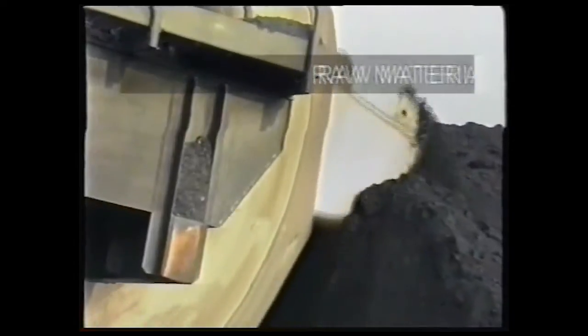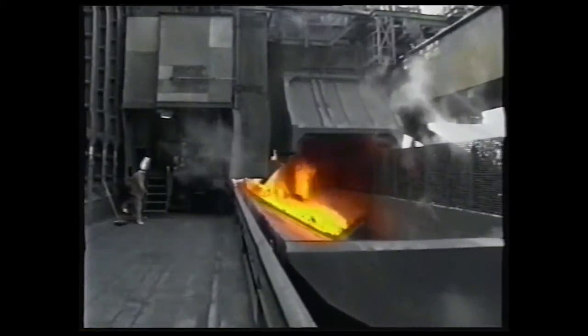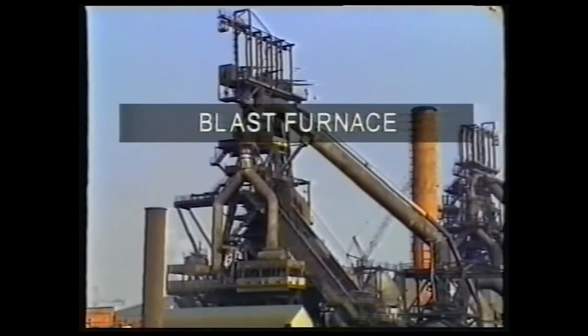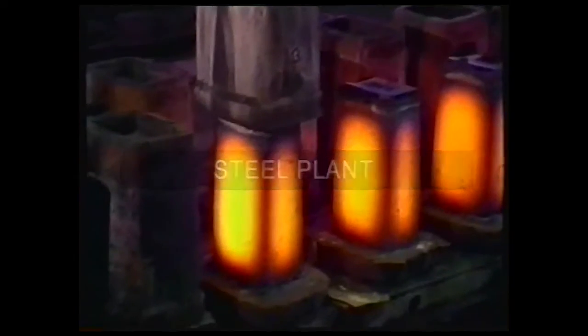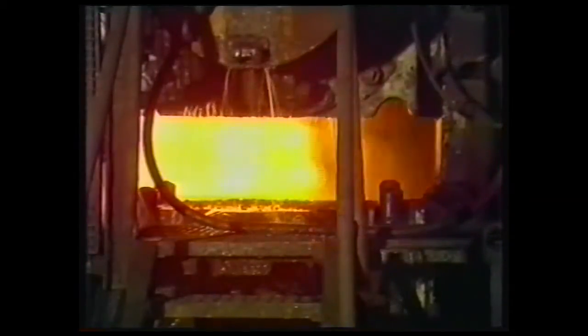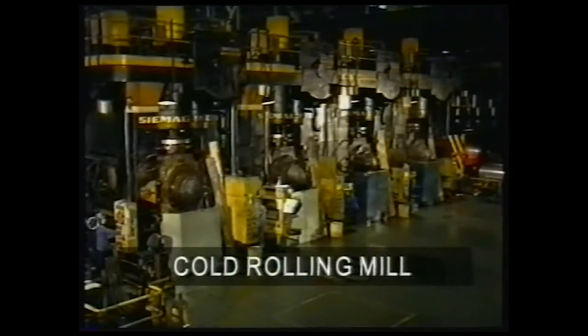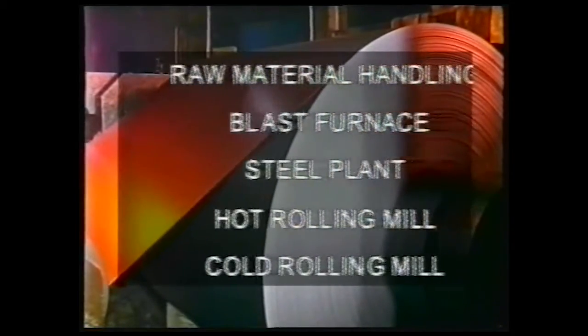Steel production starts with raw material handling. Coal is turned into cokes and iron ore is crunched. A blend of these is fed into the blast furnace to produce pig iron. At the steel plant, pig iron is converted into steel slabs or ingots. The hot rolling mill rolls them to a flat steel plate. Finally, in the cold rolling mill, the thickness of the strips is reduced further to anything between 0.15 and 3 millimeters. The vision system to be described operates in the hot rolling mill.